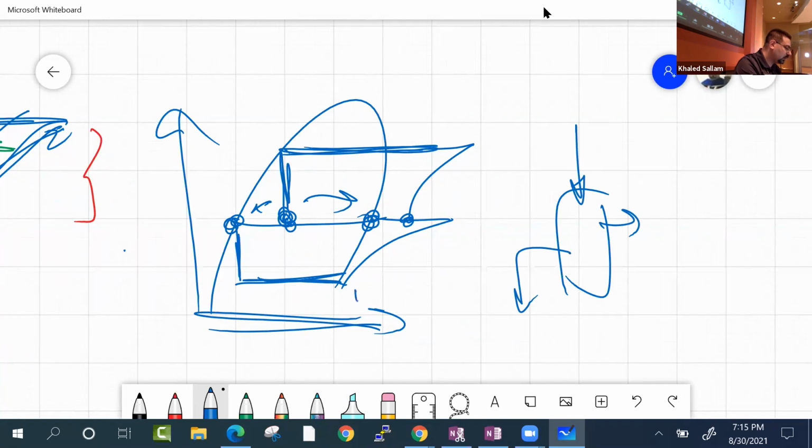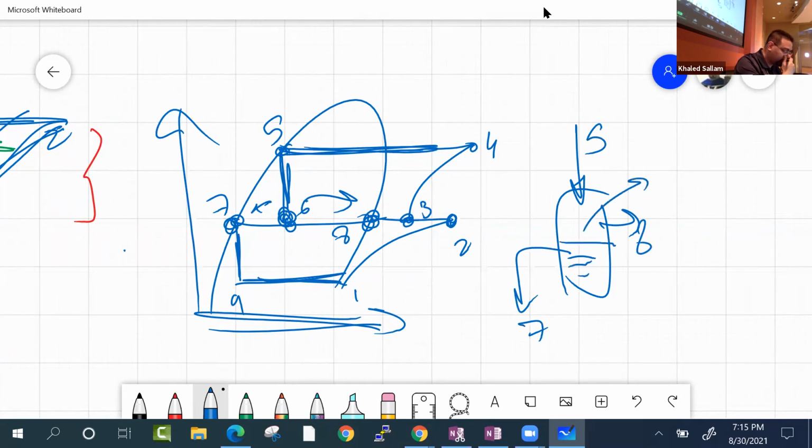So this is 1, I guess now 2, and 3, and then 4, and then 5, and then 6, and then 7, and then 8, and then 9. So you come here at say 5, and you separate into 7 and 8. The liquid goes down and the vapor goes up to 8. And that 8 meets with, there's another compressor here that takes you to 2, and 2 and 8 mixed together become 3. So that is the cooling in the middle, recooling or something.